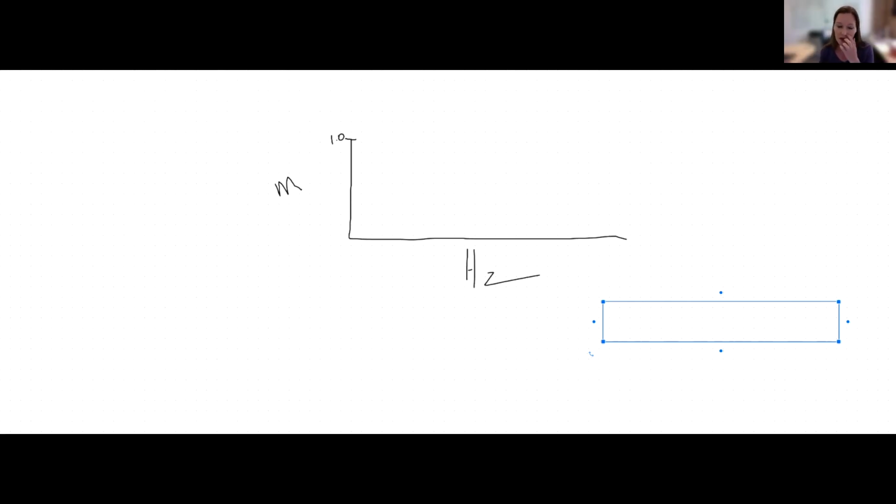But another source that's more common in our setups is that if we are measuring sonomicrometry at the same time as EMG, the sonomicrometry system is sending ultrasound noise into the body, which the EMG signal can pick up. And so you will sometimes have those frequencies. They tend to be higher. I can't remember, Lauren, if you remember offhand what those frequencies tend to be, but I'm going to say above 1,000 hertz, maybe something like that.